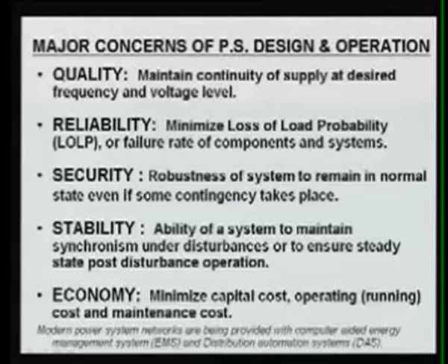But if there is any contingency which is going to come in the near future, what will be the state of your power system? If you are planning in such a fashion that the effect of that contingency will not lead your power system to an abnormal condition, then we can say our power system is secure. However, reliability is related to the probability of outage of equipment. Again, that is the equipment corresponding to your branches and your power outages, etc.